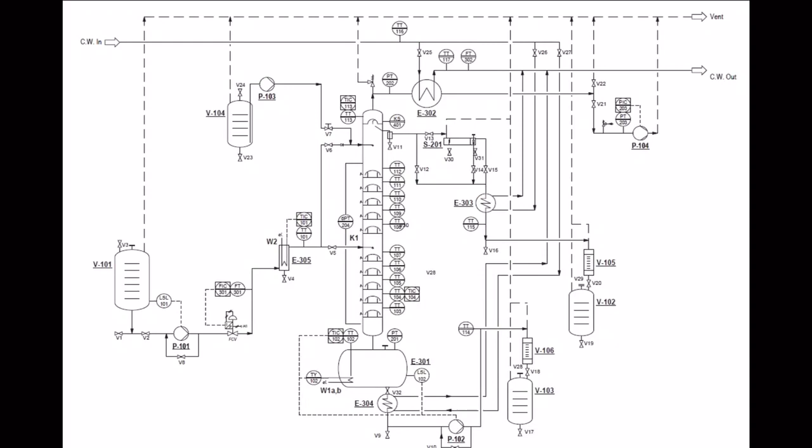Then after recording the refractive index, turn off the heater and wait for approximately 10 to 20 minutes and allow the DC unit to achieve a new steady state. And finally, drain all the mixture in the top as well as the bottom tank.